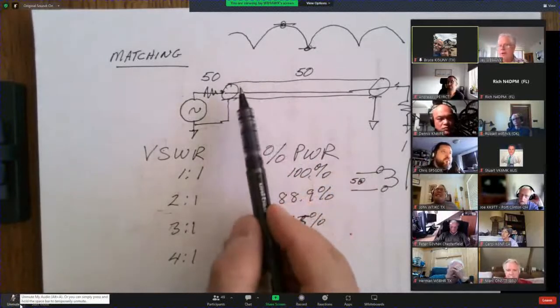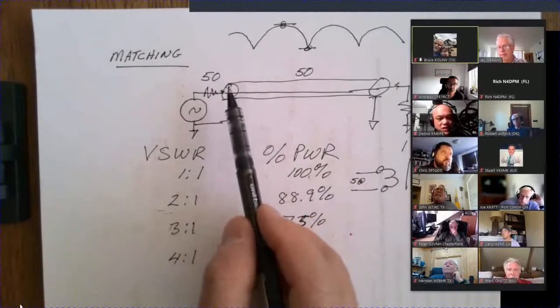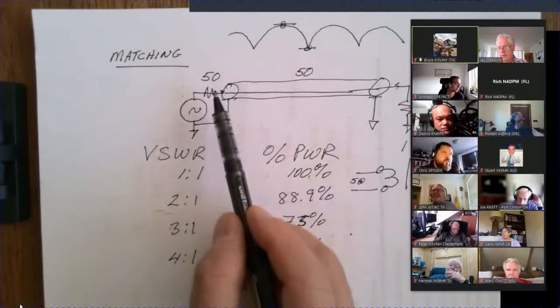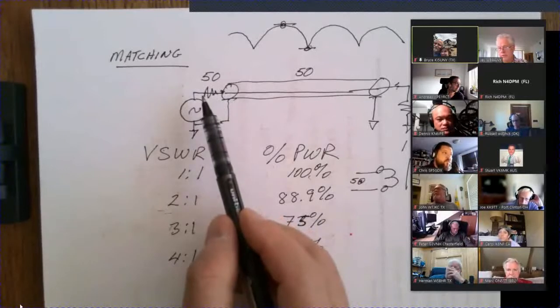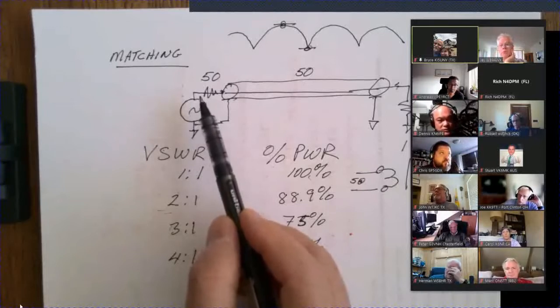So, what's the difference? What is one seeing versus the other? The meter itself shows very good SWR, less than 2 to 1, probably around 1.2. Good. And the SWR from the transmitter is considerably higher, up over 4. Ooh. And nothing has changed except I've switched out the meter for the transmitter.